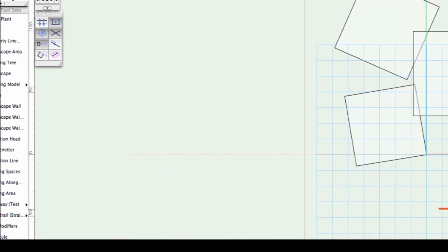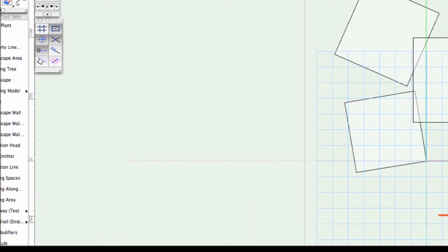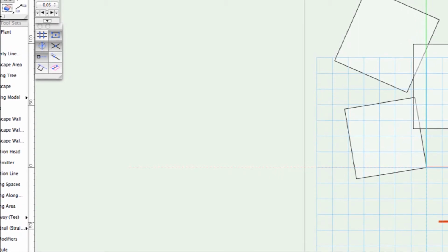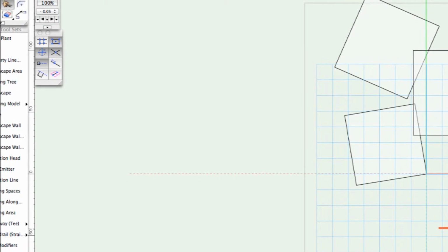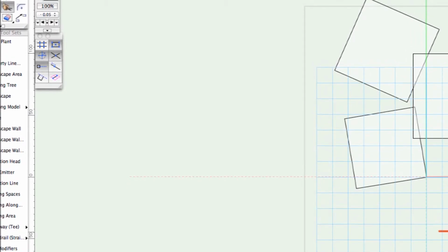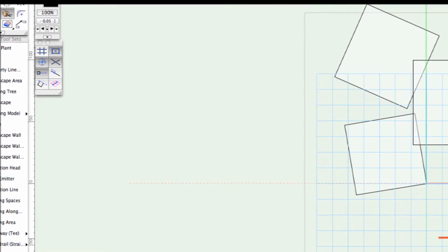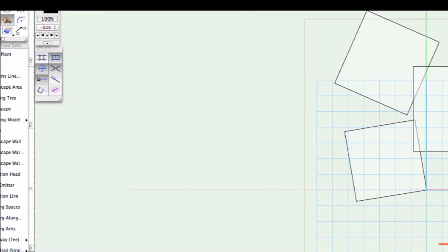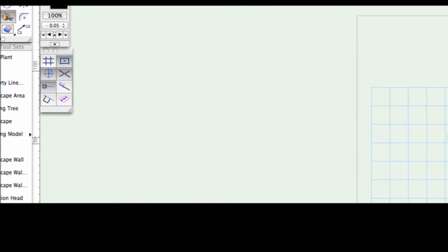Similarly to the eraser tool, the above button is the scissor tool. This enables you to also cut a segment of a line or any object, as shown in the below image. This is like the scissor tool in Photoshop, however I've always struggled to use that tool. In Vectorworks this seems pretty much self-explanatory, as it highlights the area you want to delete. Yet the tool I think I would prefer is the eraser tool, as it takes out more of what you want to delete rather than doing each little part.